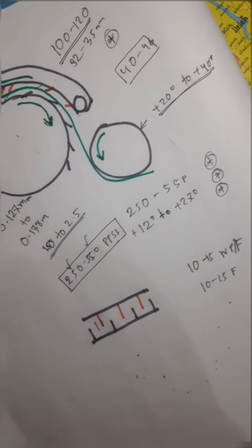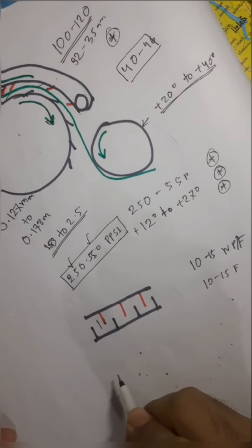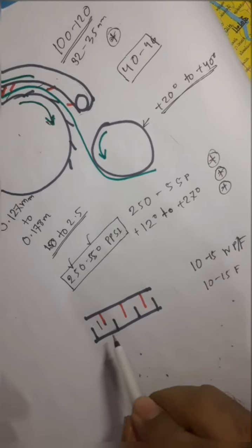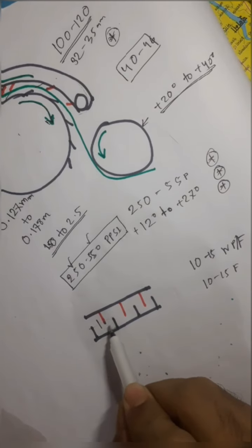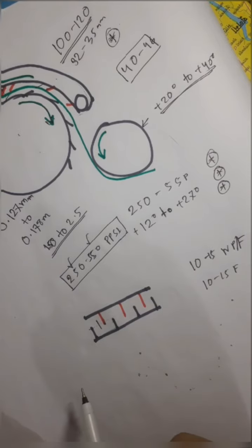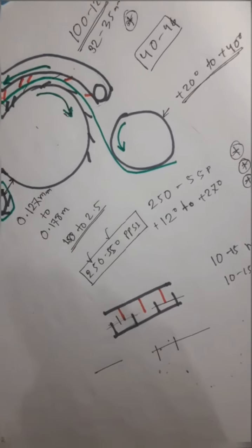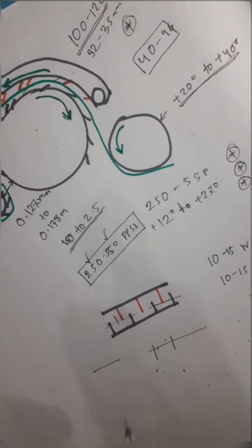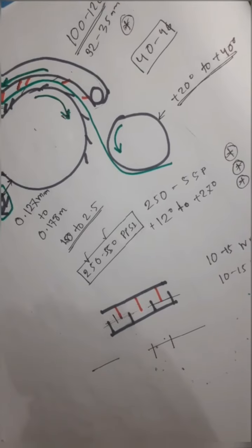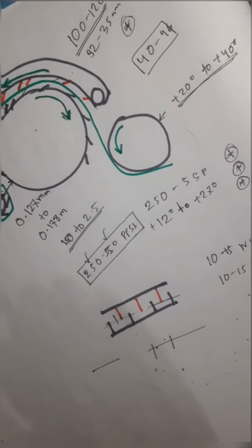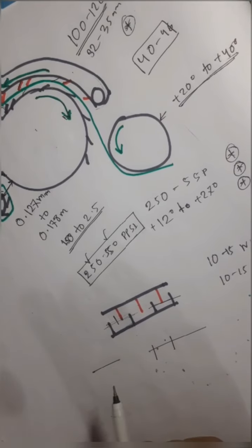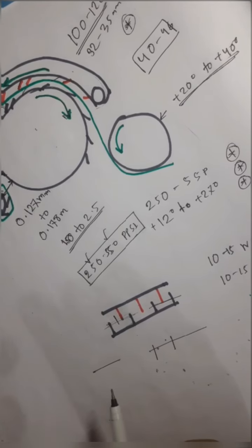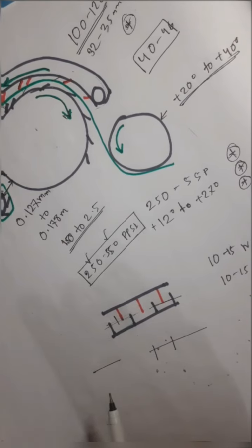And now the second one, neps opening. Actually neps opening is also done the same way, by the action between flat and cylinder. Now in terms of short fiber removal, a short fiber has less contact with cylinder wire and a long fiber has more contact with cylinder, and that's why a long fiber will be retained by the cylinder and a short fiber will be retained by the flat bar, or flat, and this is how the short fiber will be removed from this.